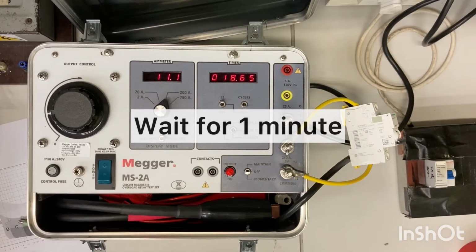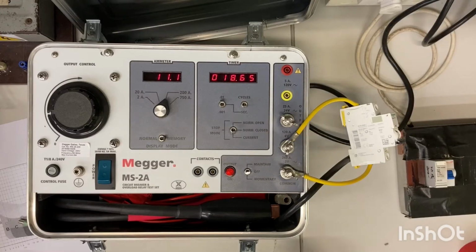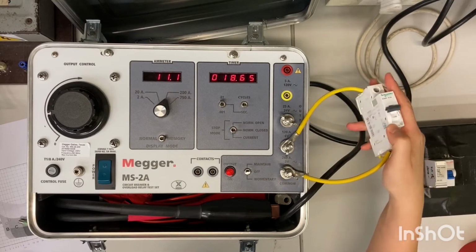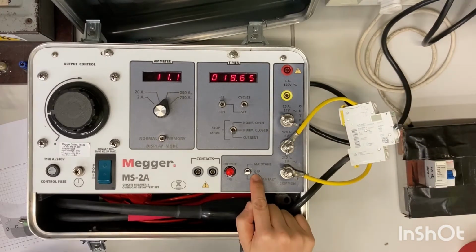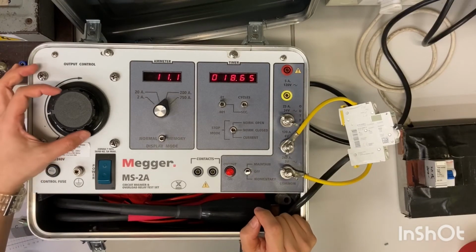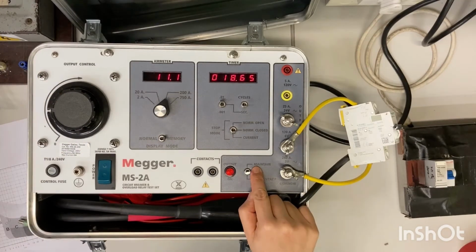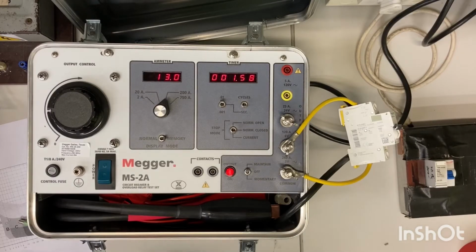And then we need to wait for 1 minute for the circuit breaker to cool down. After 1 minute, we can turn on the MCB and try another current value. The button is still at the off position. Then we can directly turn the knob a little bit to increase the current magnitude. We press the button to the maintain position to start the current injection. You can see that this time the current value has been increased to around 12 to 13 amp.